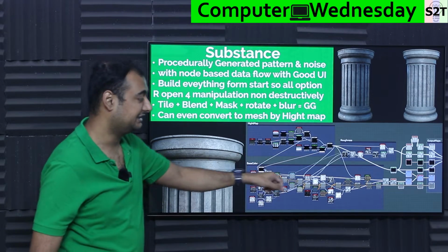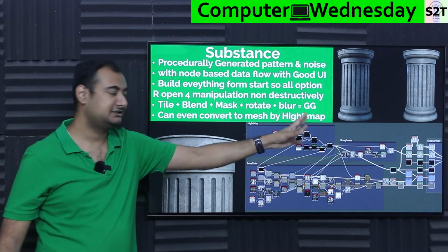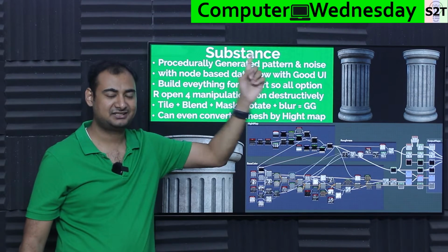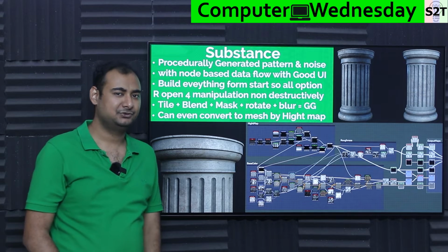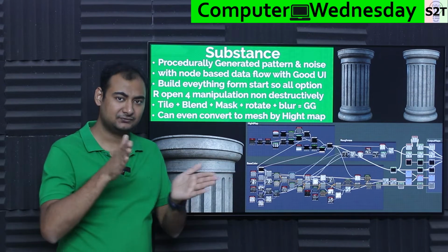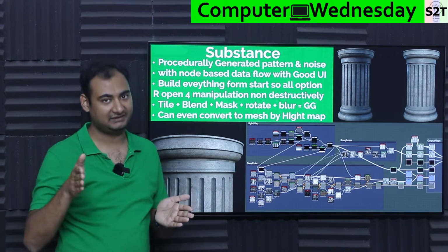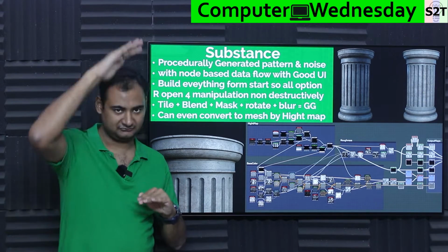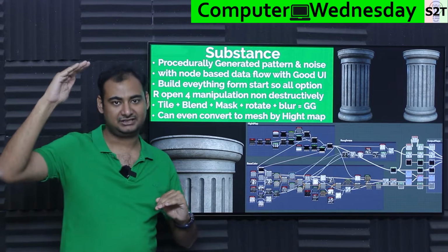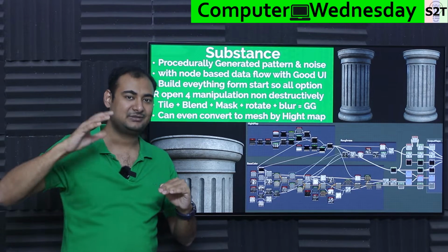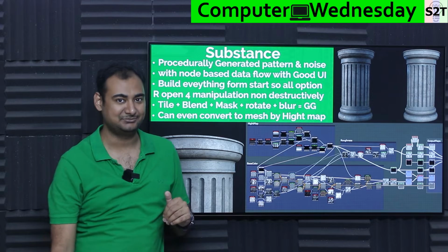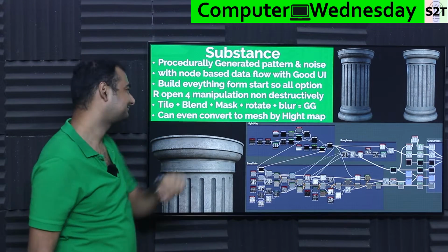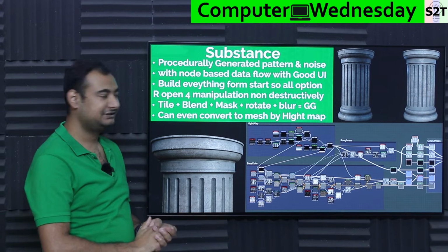So this is base color, this is height map, this is roughness, and all that is combining into output, and then output is giving you this geometry. You may wonder, how the heck can a texture give geometry? Well, there is a map known as a height map, which physically moves vertices based on the pixel value. Basically take your pixel value, 0 to 100. Imagine you have a vertex that can adjust to it. And now imagine you are projecting a height map onto it. If you do that on a cylinder, voila, a pillar. So we can do everything from the start.